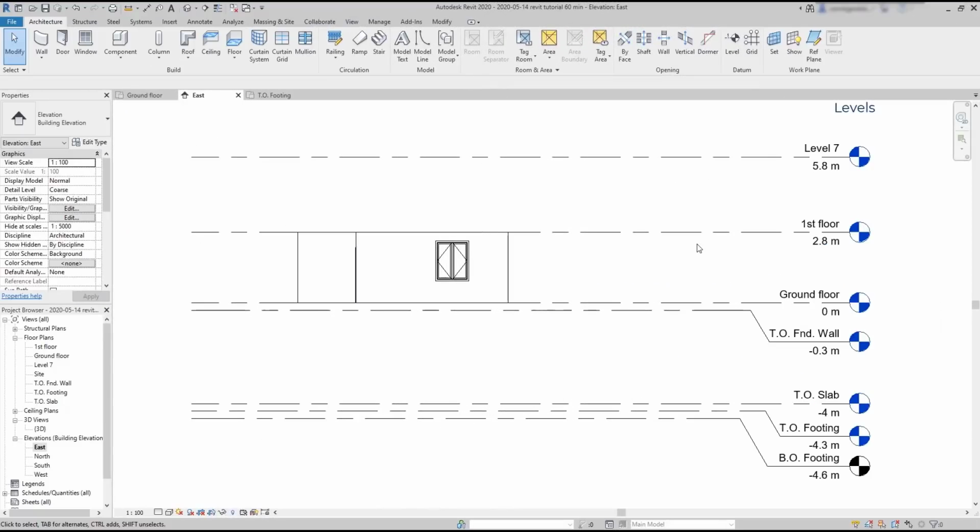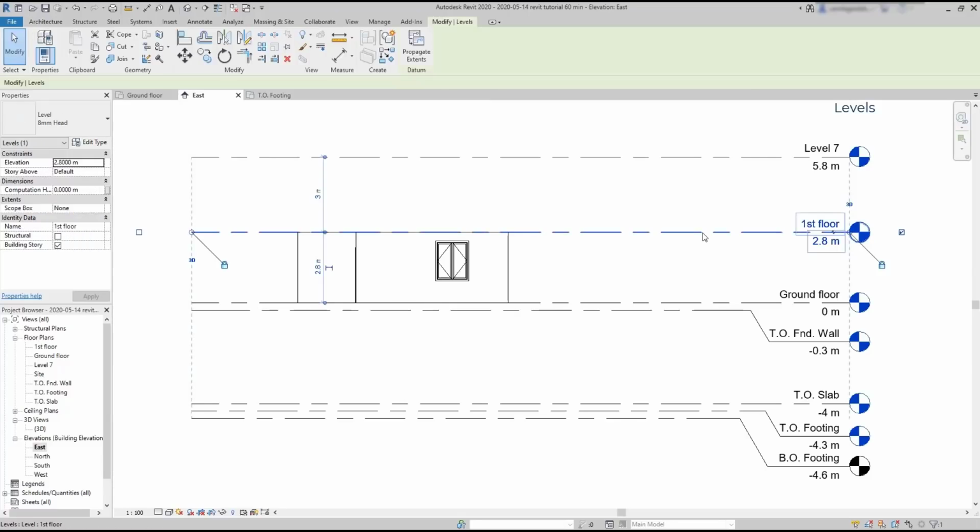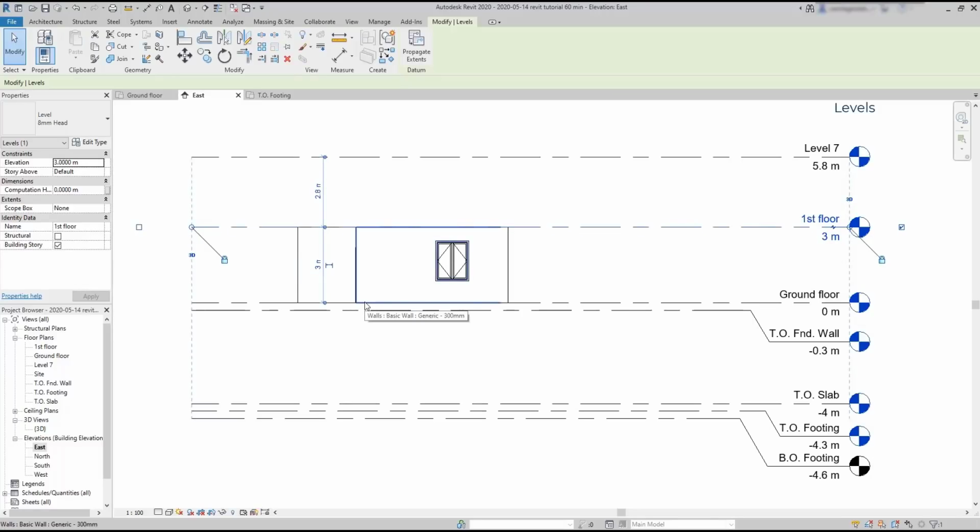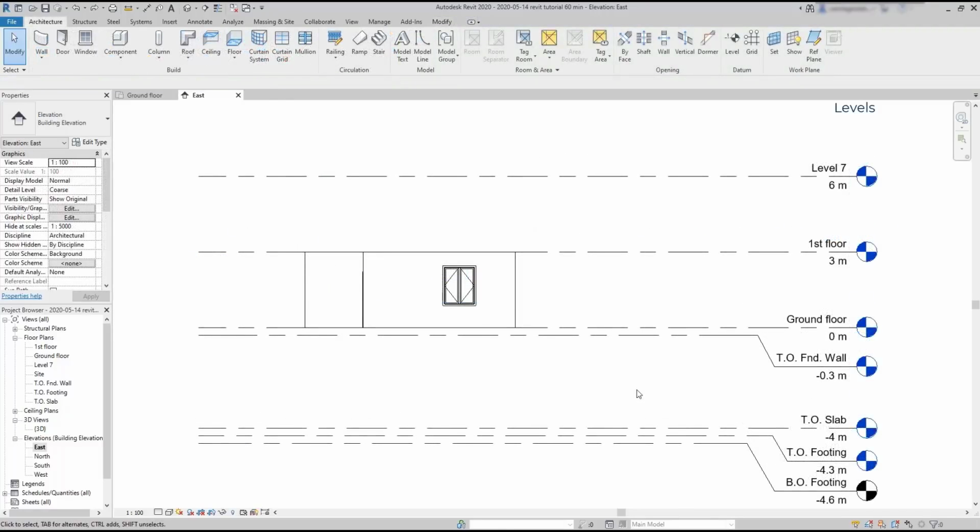To modify the level heights, I already showed to you. It works the same way as for other elements like walls. Click on the one you want to move, and then change the lengths of the temporary dimension lines that appear. Now let's have a bit of practice. If you want, you can use this image. I attached it in the description of this video to make this short exercise.